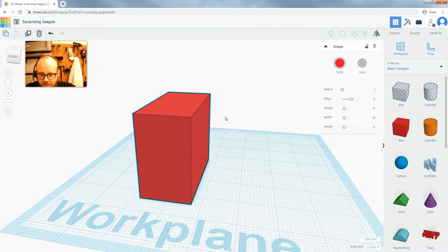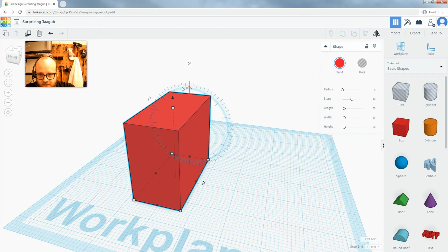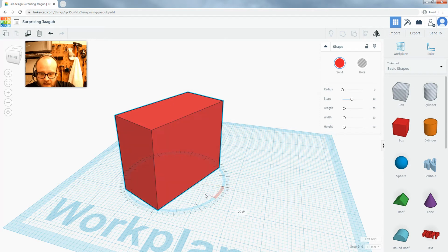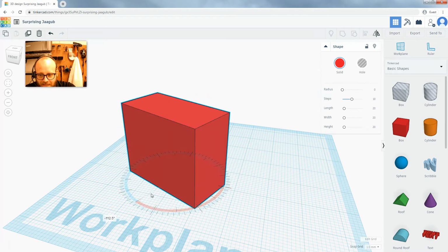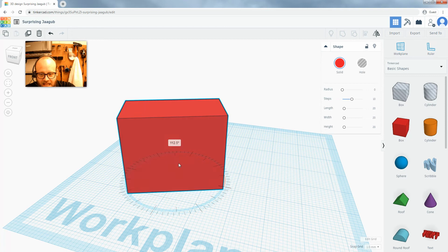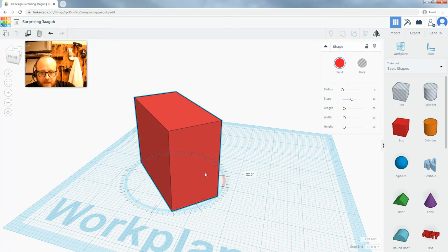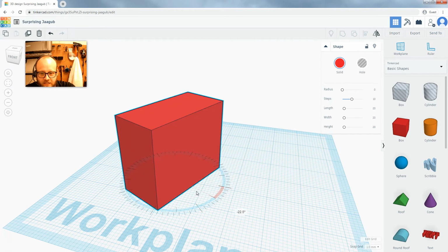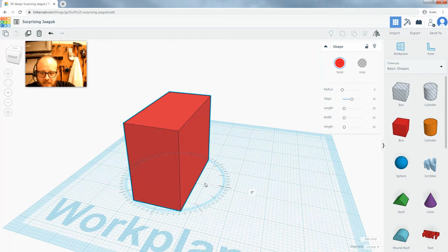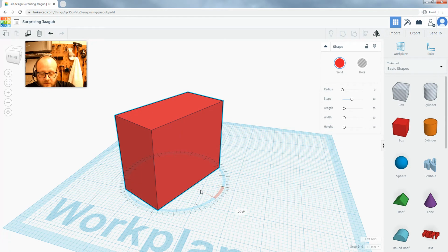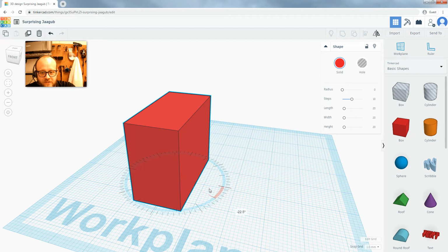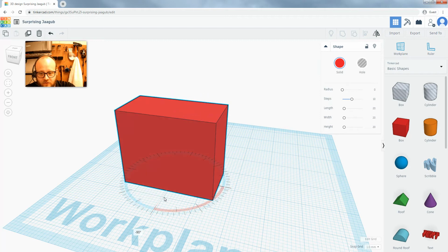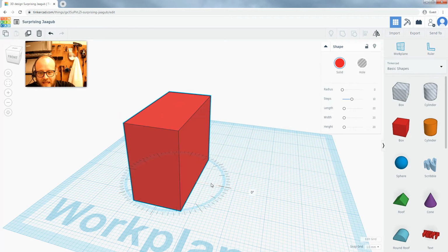The next things you can see if you look at this object are these 3 little curved arrows, and these are the rotation options. If I click and drag while I'm inside this hash marked circle, it's going to jump by units of, excuse me, it's not 5 degrees, it's 22.5 degrees each time. So it's divided into a circle based on that 22.5 degree mark.